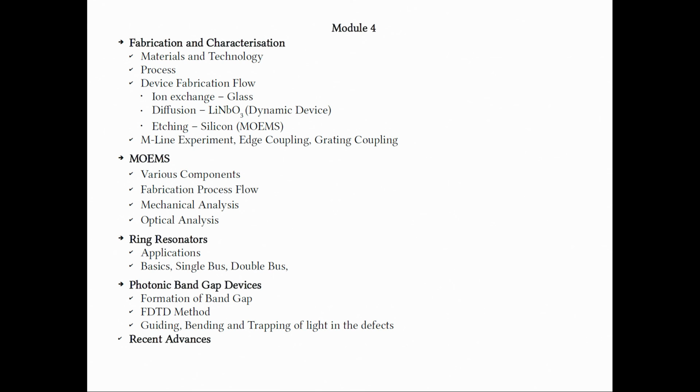in particular which we have not considered in this course, such as photonic integrated circuits on active materials like gallium arsenide, indium phosphide, and so on and so forth. This is important in the future because these are the materials which are commonly used for optical engineering applications, and more importantly you can make lasers and other active devices on these active substrates. So that is the importance of using compound semiconductor devices.